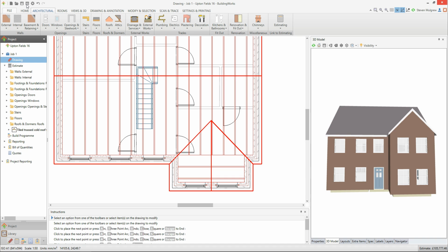Over to you. Draw an apex roof which adjoins a roof or wall. Go to the Architectural tab, click the Roofs drop-down menu and select a roof type. Choose a specification which suits your job, then select the roof configuration. Enter the pitch of the roof and review the other dimensions, including the valley connection type if appropriate, before clicking Finish. Follow the on-screen instructions to indicate the width of the gable.